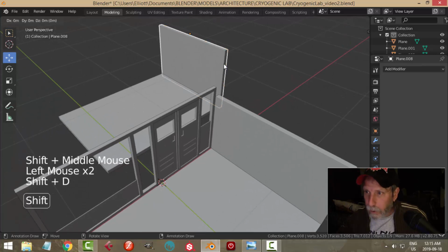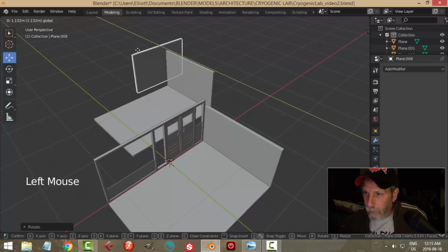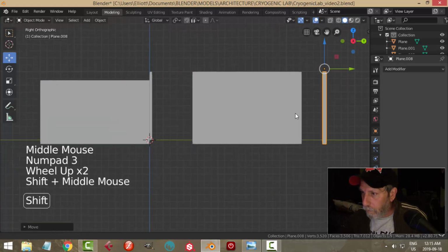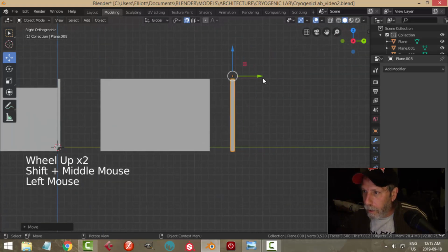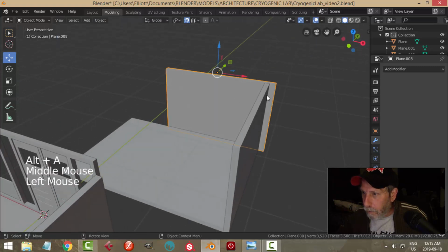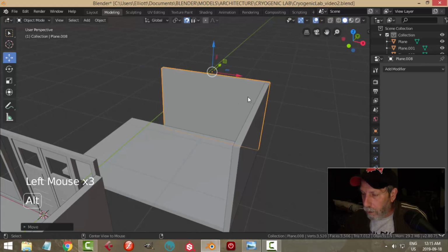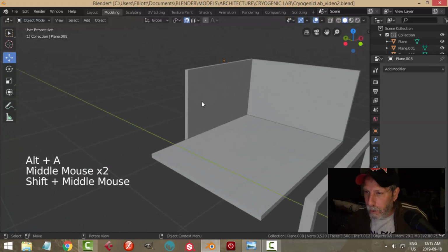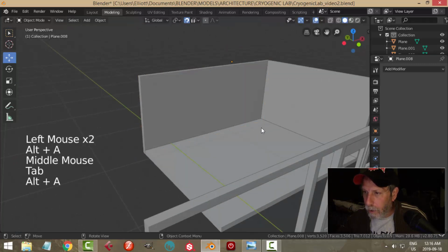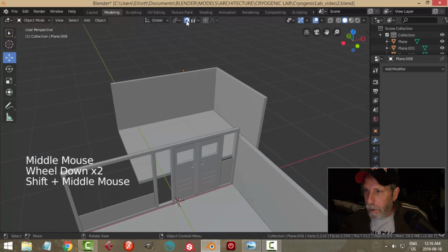And we'll do this, Shift-D, rotate Z 90, and do the other one here the same. Snapping. Snap to that edge. And then we'll come in, grab that face, and snap to this edge. So let's see, we got that. Now let's turn that off.